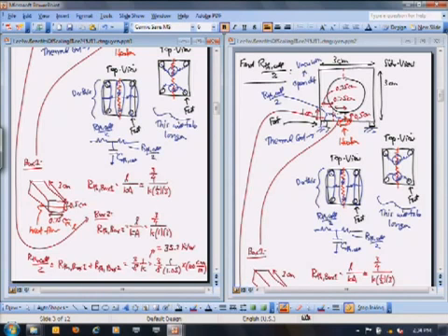Again, it's just a geometry problem, but we're making approximations to get that geometry. This is back of the envelope. If we want to be accurate about this later on, plug it into finite element, which you'll be playing with this semester, and let the finite element program get the exact answer for you. But for you, you want the back of the envelope. You want the quick solution to know whether this is a good direction or not to go in.